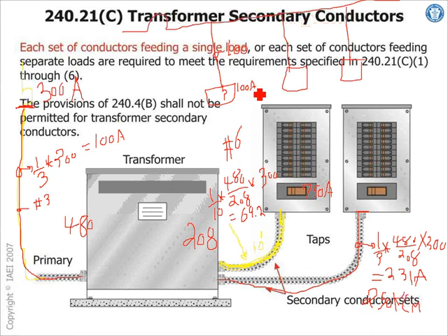So whatever conductor you tap for a mile, and I'm exaggerating here, as long as the conductor is 100 amp and you landed 100 amp at the end of it, the code is okay with this. That's where utilities go into tapping, not like we apply to utilities, but you can tap overhead, and as long as you protect them, they land in an overcurrent protection device. So the conductors have to be protected from physical damage in an approved manner.